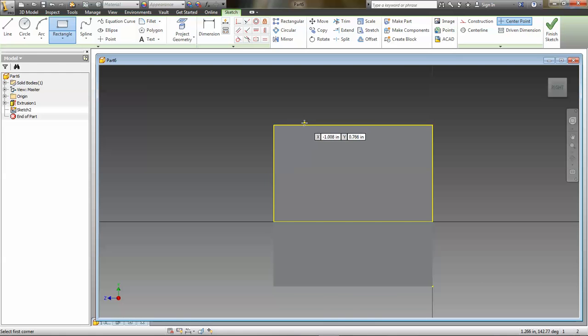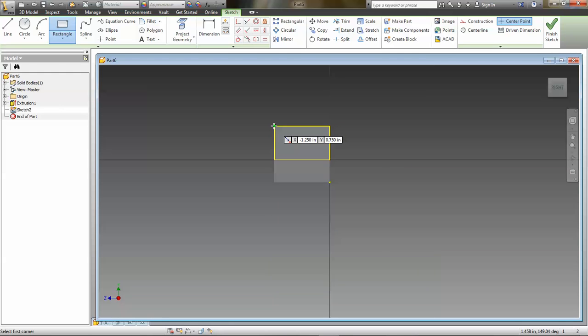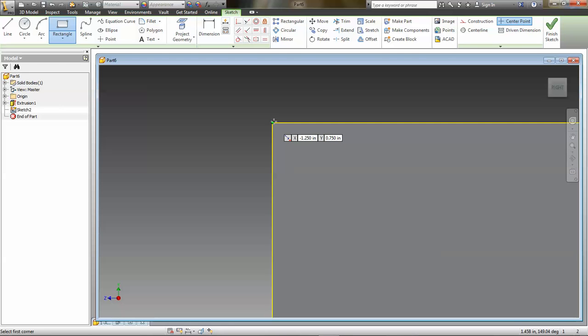So this notch here is, if we go to the upper left corner from this view, we see the x coordinate is minus 1.25 and the y coordinate is 0.75. We know we want to be, I think, 0.25 inches from there. So minus 1.25, and then we're going to be 1.0 here, right, is going to be the starting point.